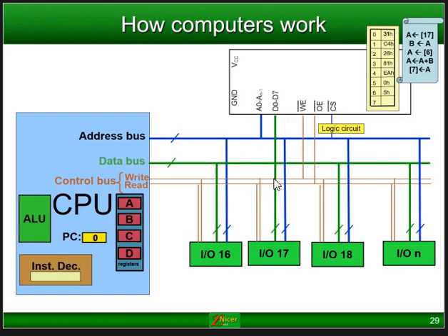So what we have on this specific slide is, again, here's your CPU with the address bus, there's a data bus, there's a write line, there's a read line, and as you can see, it's connected. The write line is connected throughout to all the IO addresses, and also it's connected to the memory here. And inside this memory, at address 0, we have a value of 31 hex. Now, depending on the microcontroller, forget about the 31 hex. It's just that inside there's an instruction. That's basically what it means.